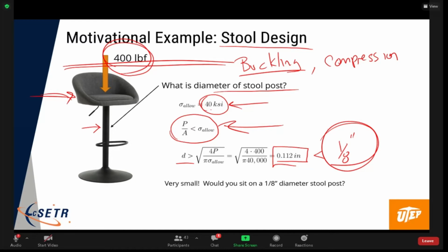Live, right? So I'm just putting a force on axially, trying to compress it, right? And it wants to deform like it is in bending, right? It doesn't compress like we would expect with P on A, right? With P on A compression, you'd expect the length to change because every little element compresses down, right?